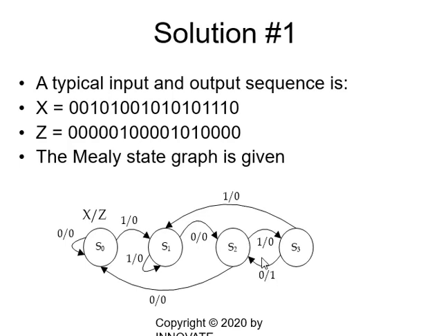So if I receive 1, 0, 1, 0, 1, 0, 1, 0, it will give me 1, the Z will be 1 in every cycle. So you will get 1, 0, 1, 0, 1 for Z. And to do that, from S3, I went to S2 to allow overlap.